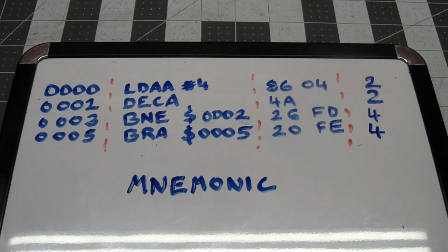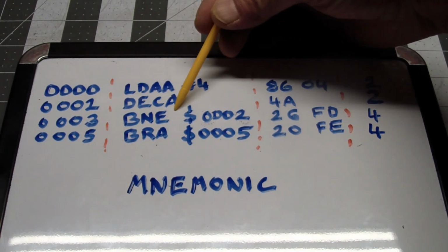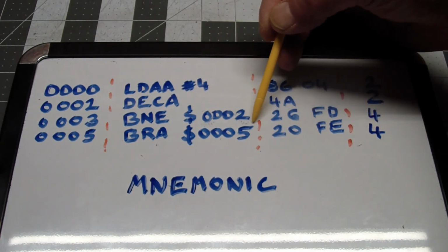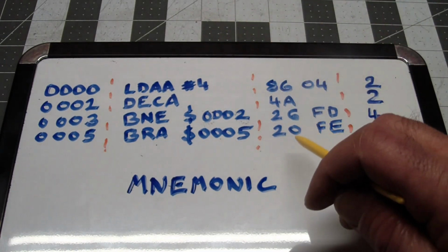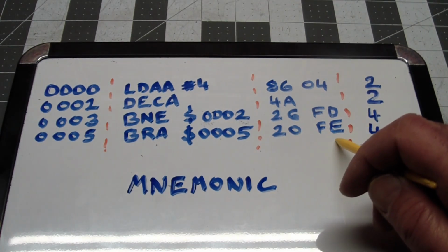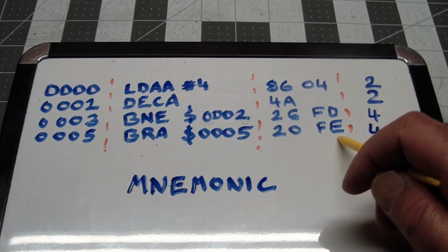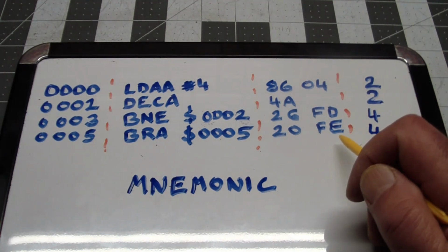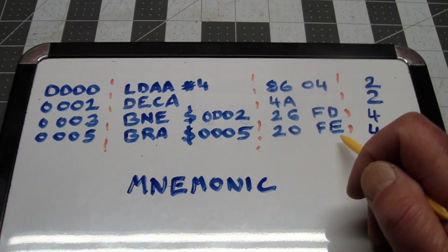And the only other thing you may be wondering about is, so we have a branch here or a branch here, and there's a 16-bit number here. So then how come we only have one operand which can only specify 8 bits of value? And that's because the branch instructions are basically space savers. The number they use is a 2's complement hexadecimal byte.